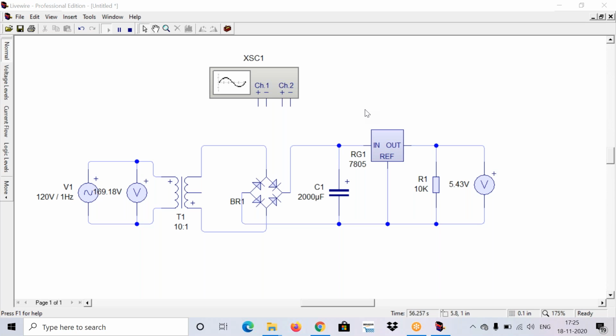That is the reason we use a bridge rectifier. In a bridge rectifier, at a time, two diodes will be operating. If two diodes are on, the remaining two will be in off position. Like that, if we use a bridge rectifier, the output will be perfect. I cannot explain you all the theory part. We just need to do more circuits. If you are fast, I will give you the circuits, so that we will be designing the PCB layouts for these circuits. Is that clear for everyone?